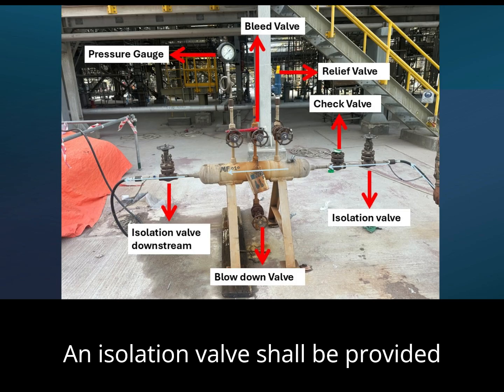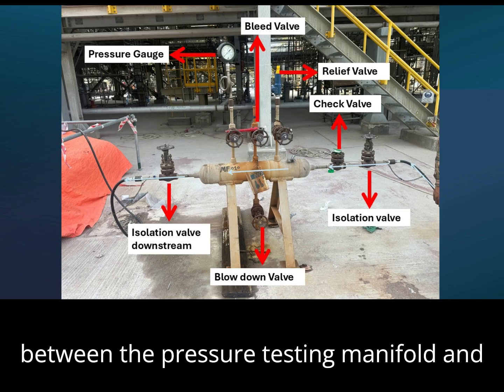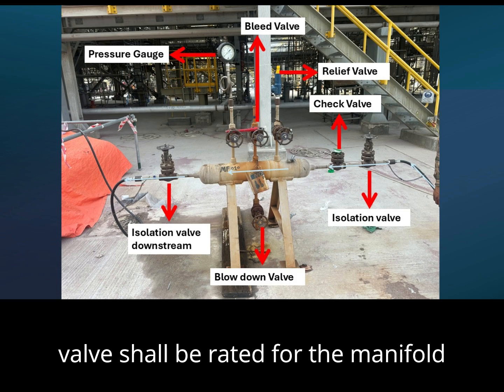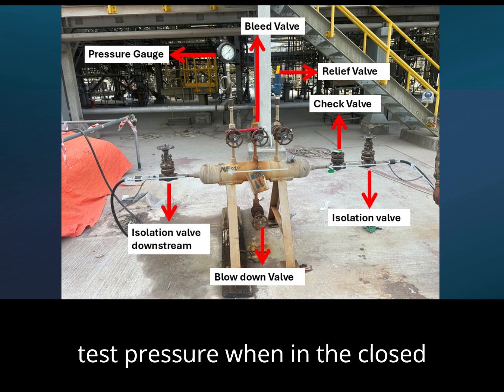An isolation valve shall be provided between the pressure testing manifold and the system being tested. The isolation valve shall be rated for the manifold test pressure when in the closed position.